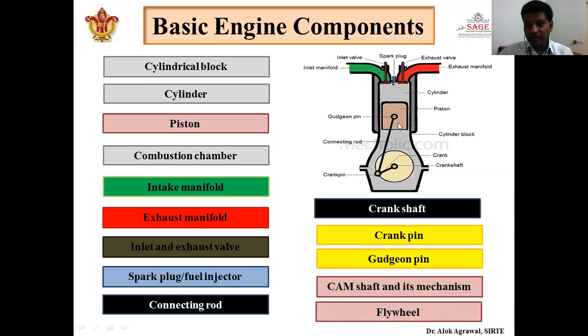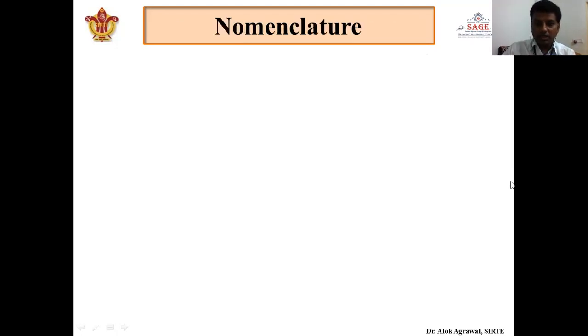The function of the flywheel is to store energy and deliver it when required. When the engine is not working or is under some serious condition, the energy is taken from the flywheel. Otherwise, a part of the energy which the engine produces gets stored in the flywheel. So these are the important components of an IC engine.